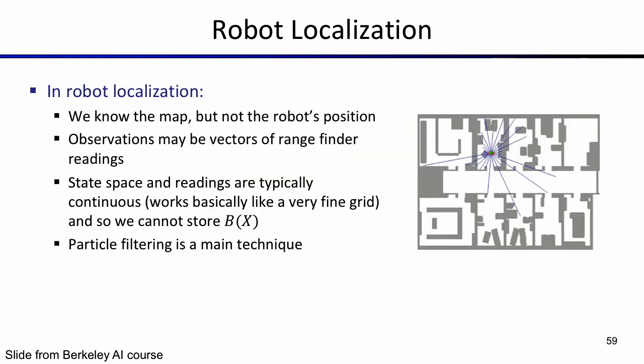So this is one application of particle filters for robot localization. When I saw this problem for the first time, I thought that it would be very simple to solve, because there are devices that you can install in the wheels of a robot. They're called encoders, and those encoders are very precise. And in this case, it would be very simple to track the position of the robot in a map if you know how much the robot has displaced in the map.